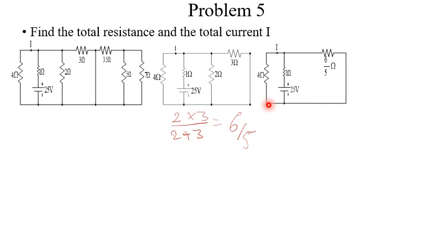Let's do our drawing. So we can start from here. We pass through this resistor, come and pass through the second resistor, all the way back to the first resistor without meeting any third element, meaning they are in parallel. So we also use our parallel formula for that. So it now becomes 4 times 6 over 5 all over 4 plus 6 over 5, which gives us 12 over 13. Then we'll redraw our circuit again.